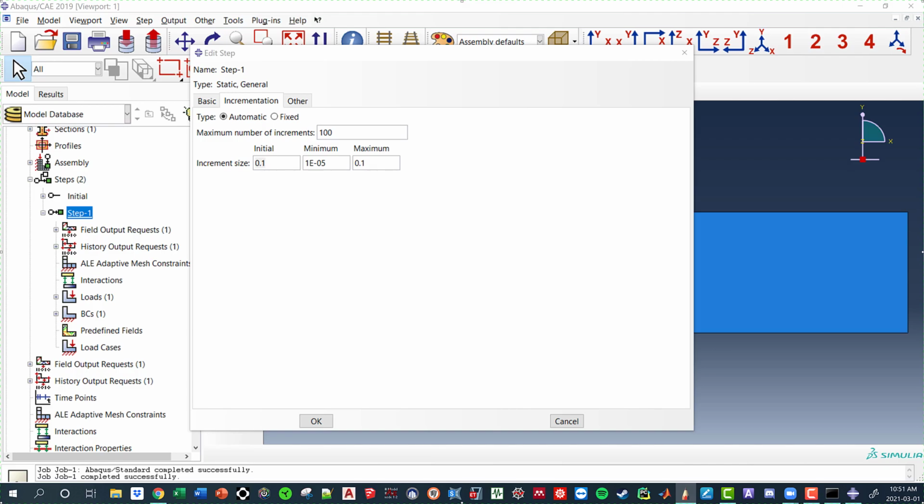This right here is the step. So if we were to do the load percent, it's simply going to be our step size divided by our time. So in this case, we have 0.1 divided by 1, which is 0.1, which means that our load is going to be applied in 10% increments all the time in ABAQUS. And this is something we play with. Again, if ABAQUS is not converging, it'll start lowering that step size. Or if ABAQUS is converging rather easily, it'll start increasing that step size. And yeah, that's it for step size.